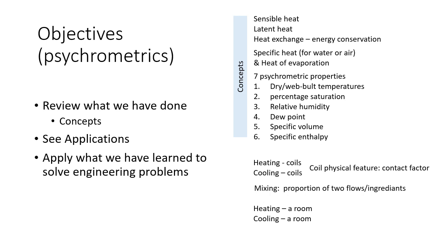Same for cooling. In the summer scenario, we have heat gain through solar penetration, through hot airflow coming into the room through infiltration, and we also have human bodies, instruments, and other office equipment, all generating heat.